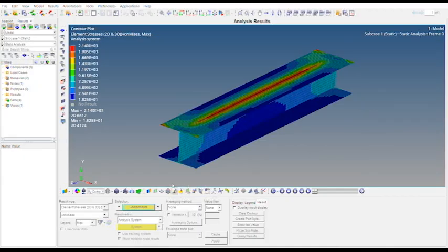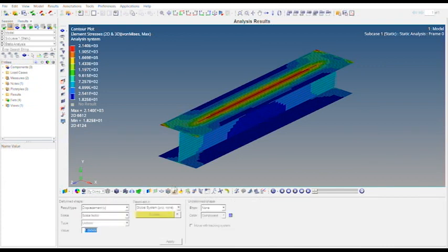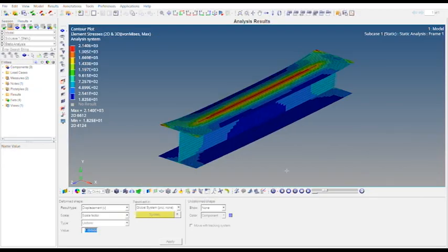The next panel, deformed. If you can see here, I'll click this. So deformed shape, if you can see here. So what is this used for? So suppose you want to see how the structure is deforming. Vector you analyzed on what directions it's deforming, but you want to visualize as a whole to see it moving. So you can just check it out here. If you can see this, you have a media player. You just click this, you can see it deforming.